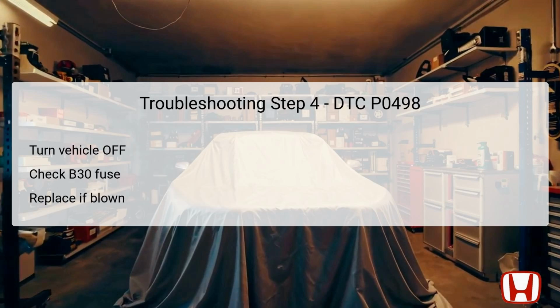The fourth step requires the vehicle to be powered off, ensuring safety while inspecting electrical components. The technician should check the condition of the number B30 fuse, a 7.5 ampere fuse located in the underhood fuse relay box.